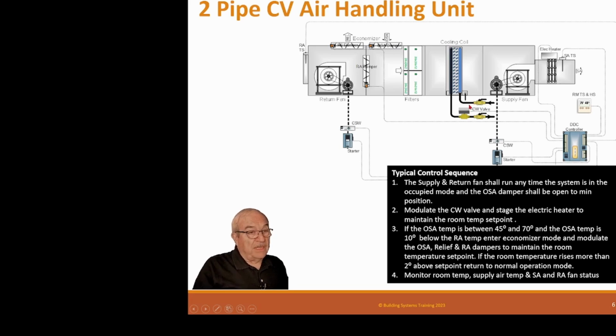And when it does that, because it's changing pressures, you have on the supply side higher pressure coming in, and then it closes, it gets lower pressure. Well, that can actually expose air, and you can't airlock a coil. And then also there's coil authority, which we'll get into later in a hydronic video. But remember, all control valves need to be on the leaving side of the coil.